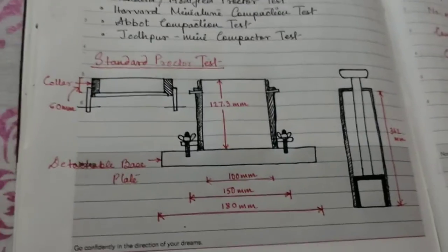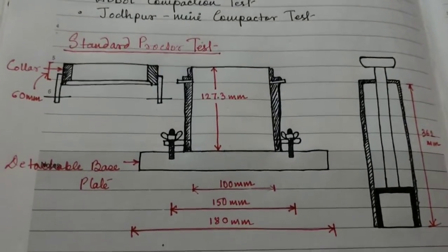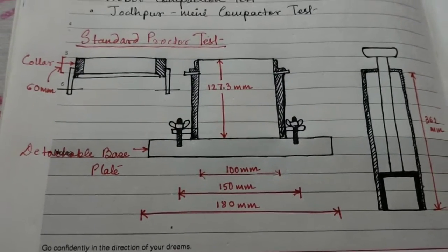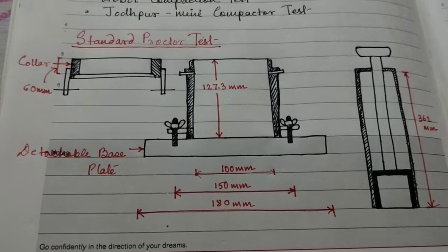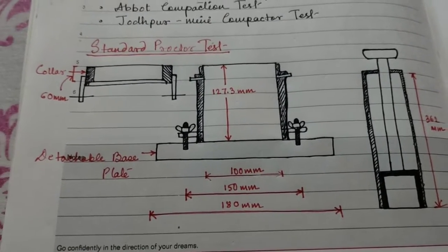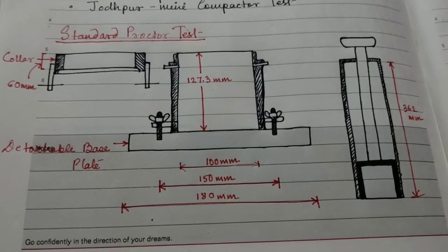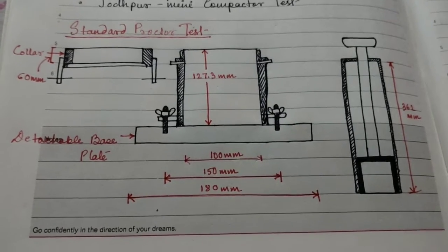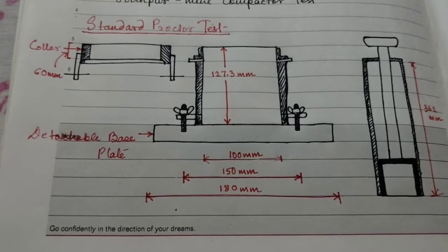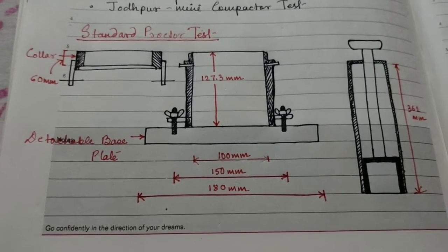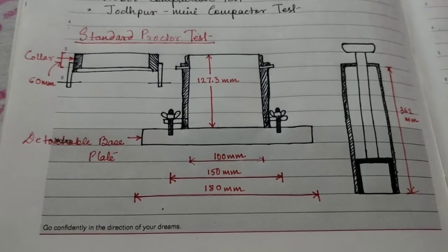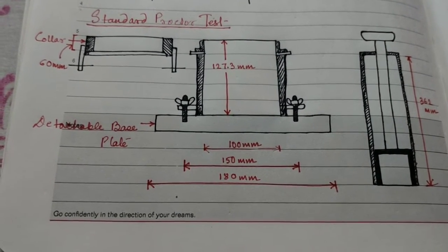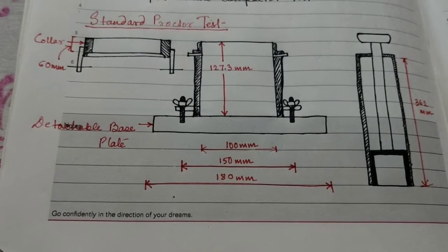You have already gone through the previous soil mechanics unit on how to calculate the water content. As you already know, the water content can be calculated from a simple laboratory experiment, that is the oven dry method, or it can be calculated in a quicker way by the calcium carbide method. But for accuracy in finding the water content, we mainly go for the oven dry method, where a sample is taken, weighed and then placed in an oven for 24 hours.